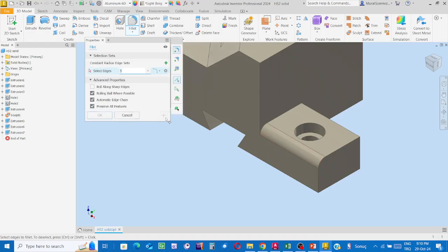Click on apply. Yes, now this edge cannot cut hands. Round this edge. Okay, and then say apply. If we round the edges, well, those cannot cut hands. It is the best solution. But if we round an interior edge, this is an interior edge, round it. Why? Well, an interior edge cannot cut hands, although it is a sharp edge.